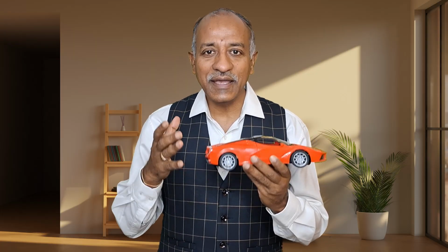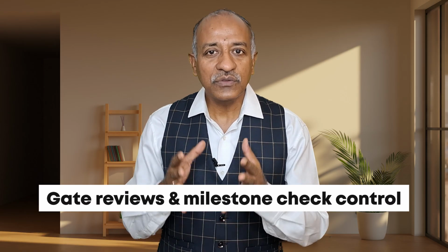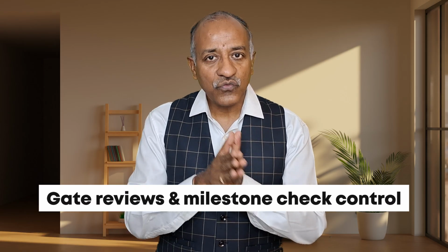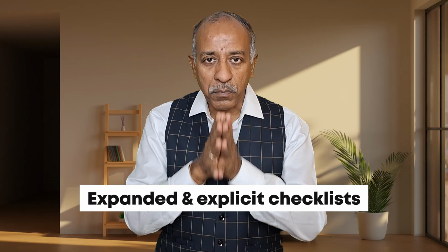So these are the 10 key outputs with respect to the APQP 3rd edition, phase 3. Now that brings another important aspect, what are the key changes when we compare with the 2nd edition. The first I already shared is that now the control plan is a standalone document. The second one is with respect to the different gate reviews. Earlier it was 5, now it is 6. Then the next one is with respect to the checklist. Now the checklists are in much more detail, asking many questions, and it helps the organization identify where they are lacking and which other things they have missed. And similarly, there are many more points with respect to that.